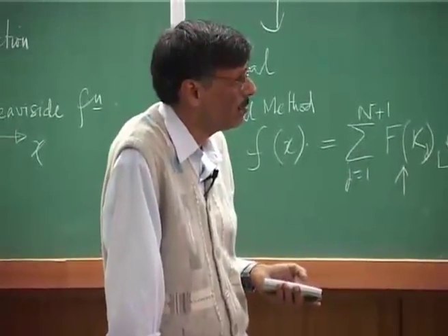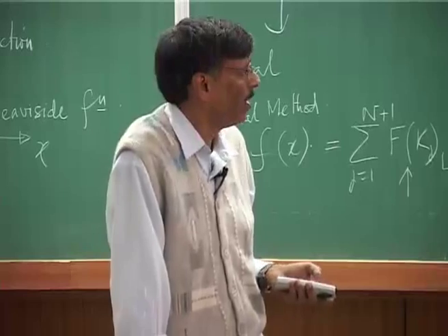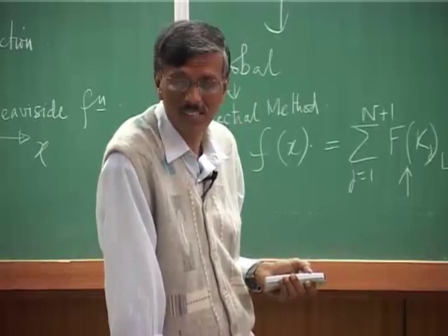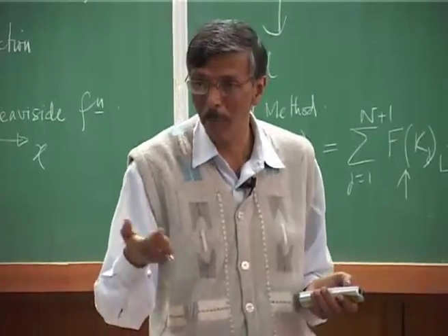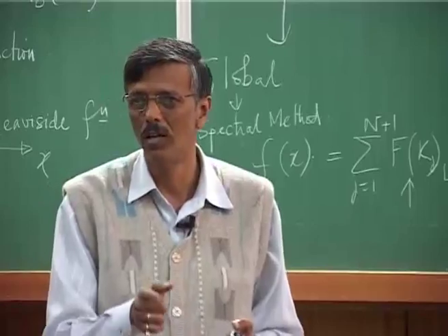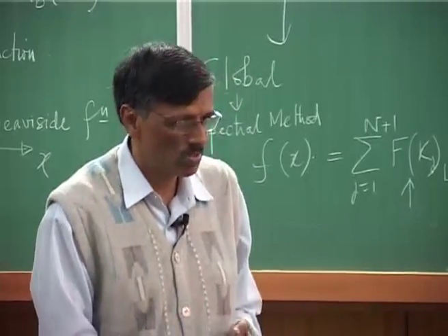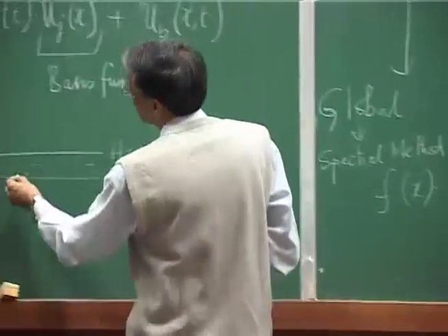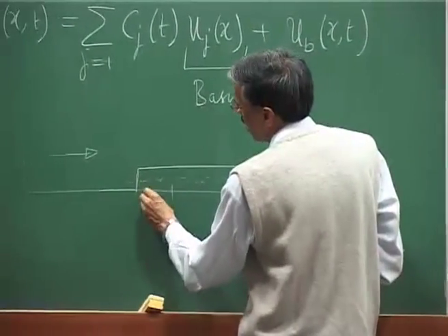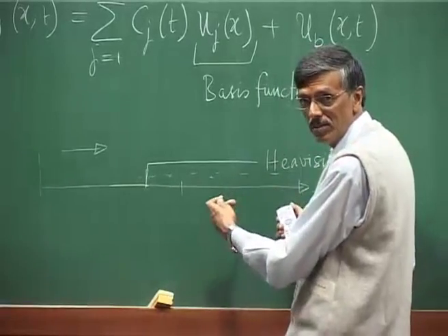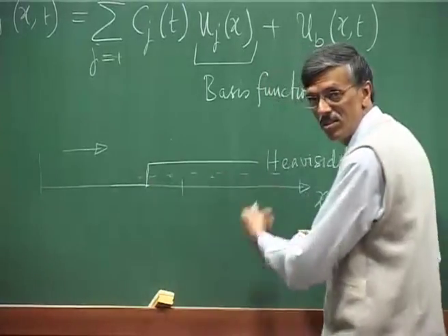However, we must be cautious about doing this. The essential ideas are nothing but similar to what we call the upwinding methods, right. That is what we did even in finite difference. You recall that we said that if the physics of the problem is such that this is the way it goes, then we do not try to do a central difference, we try to do a one-sided difference, because the information propagates in this direction.